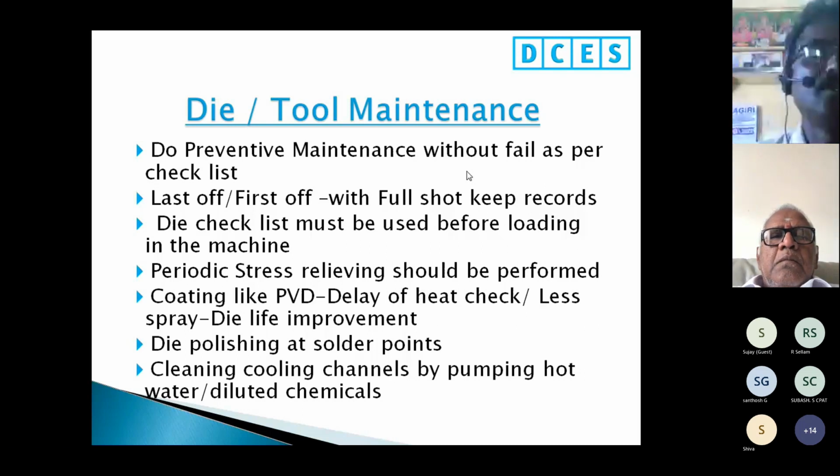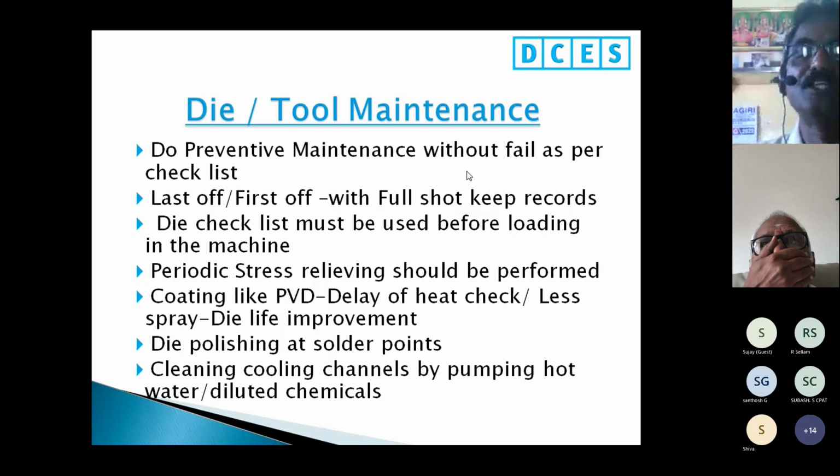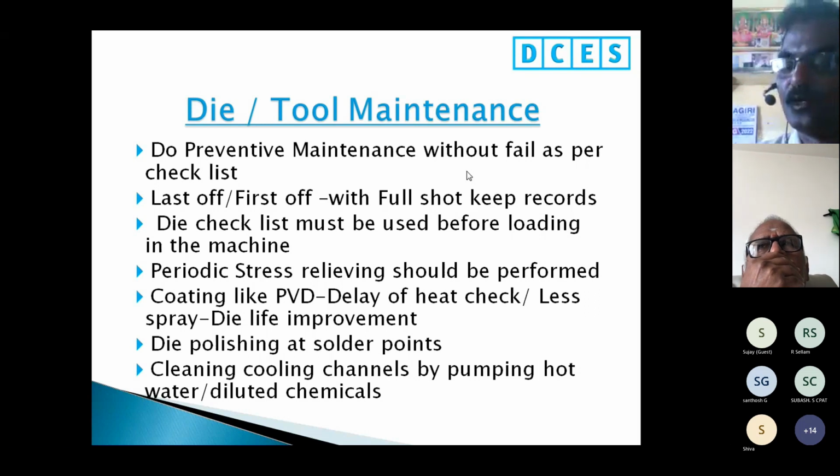So, die checklist and periodic stress relieving should be performed. Coating like PVD will delay the heat check, less spray is also possible, and die life will also improve. Die polishing at the solder points: not necessarily polish the die everywhere, as it will remove the hard film. It will help to get an easy release. So polish the die at the solder points.